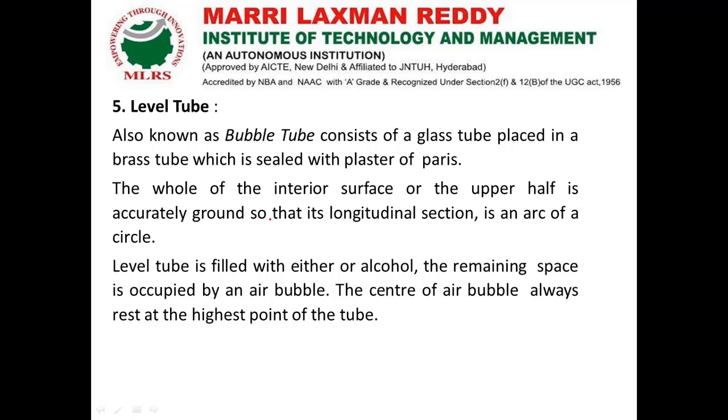Then fifth one is level tube. It consists of the bubble tube. By adjusting the foot screws we have to make that bubble come to its center position. Then only we can proceed with our entire process without any error in the readings or plane.